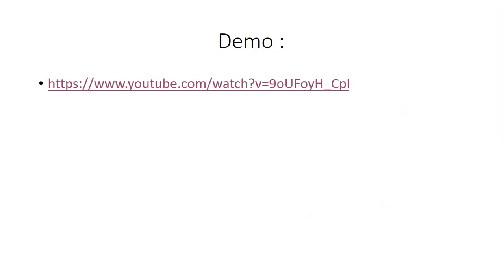This is nothing but the visible edges, and then the invisible edges we can delete, and then we can complete this construction. After which, one can see that this is going to require a 30 by 30 mm square of height 60 millimeter, and after which we have to construct the cylindrical slab. So now, to construct the cylindrical slab of 30 millimeter, what I'm going to do, I'm going to select this